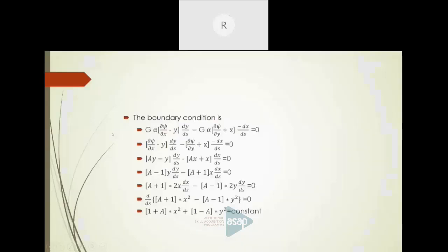Okay, now we have one more thing, the torque transmitted, because we want to know theta as well, right? We got the equation for torque transmitted from the previous slide. Now, instead of Tnx and Tny, we are going to substitute the real terms. What is Tny? Tny is the stress acting in the y direction in the Z plane. Z plane means the plane of geometry. So Z plane in y direction, that is tau yz. Similarly, Tnx is in the Z plane, x direction, that is tau zx. They are multiplied with their perpendicular moment arms and the area, and integrated over the region R.